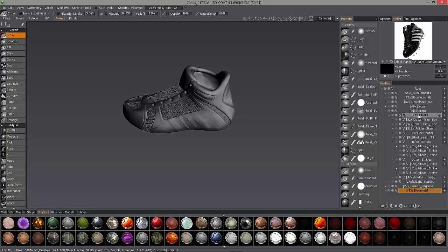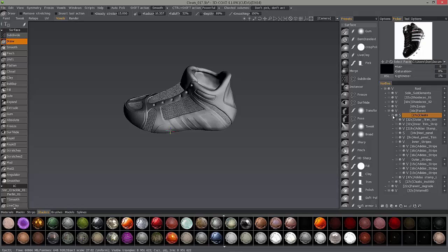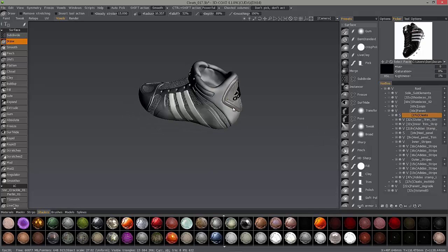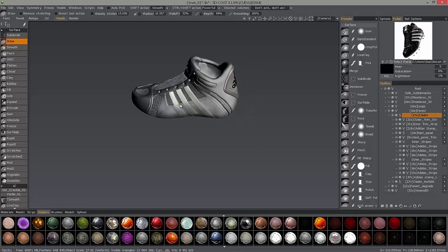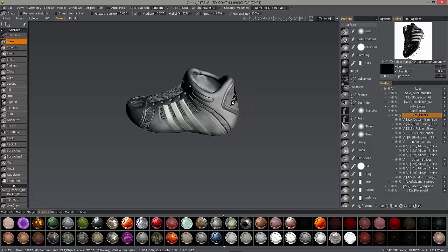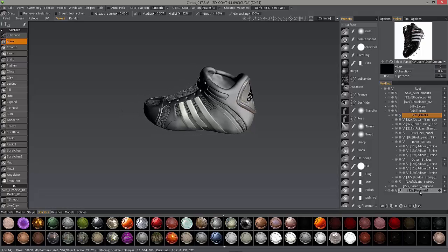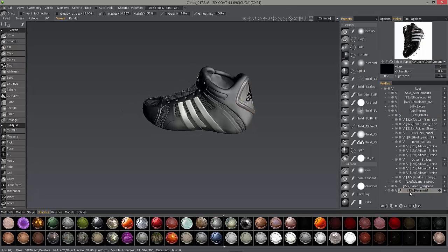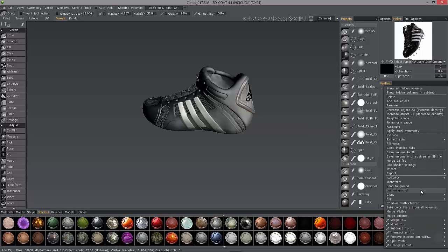in order to prevent some of the snapping issues that can occur when you have overlapping components on your model. What I want to do is create a proxy, essentially, that has all these layers merged as one, and that will prevent these errors where it snaps beneath another object. I can just choose this new blank layer that I have. I can name it Proxy. With that selected, right click and choose Merge Visible.